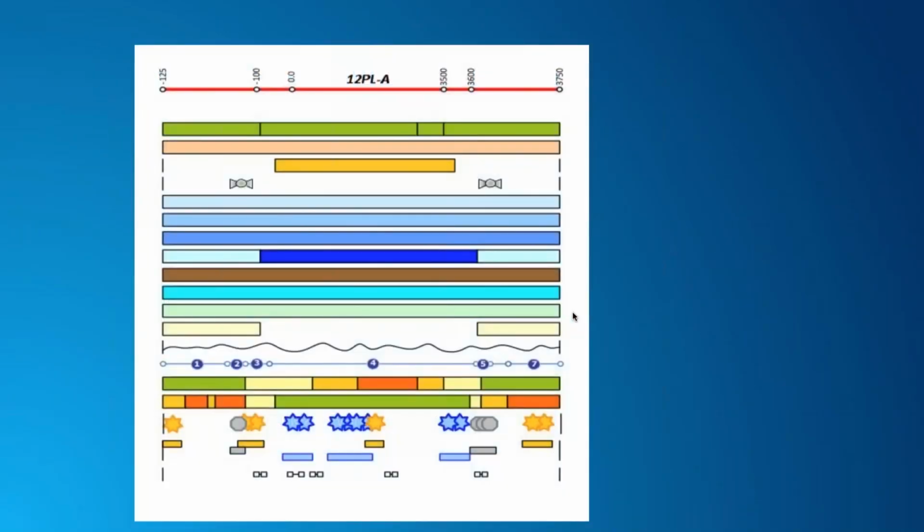And so often people say, oh, we need linear referencing because we need to support engineering stationing equations. And that's true, linear referencing does support those things, but really at its core, it's a way to model pipeline data. And the reason we use linear referencing is because oftentimes, especially in these highly regulated scenarios where we have lots of data that we need to store on top of these pipe segments, as we start layering in all this data, it's much easier to manage that data in what I call the layers of the cake, right?